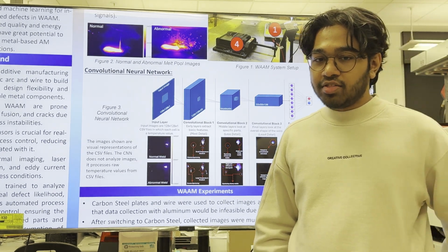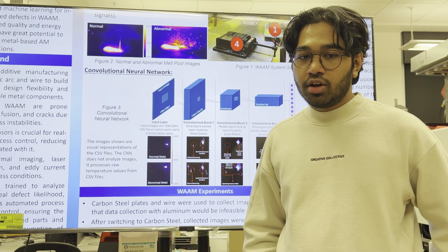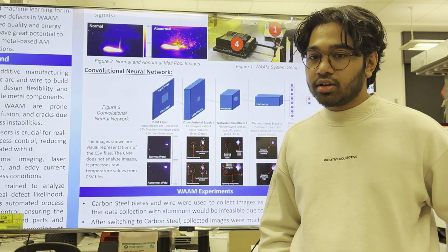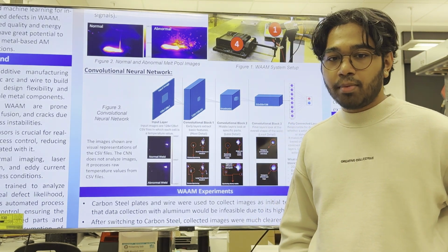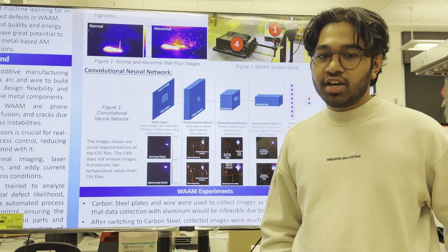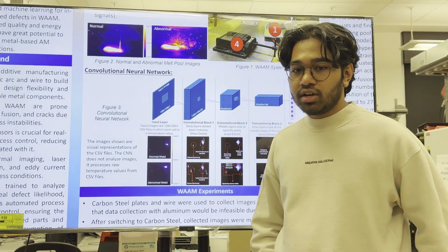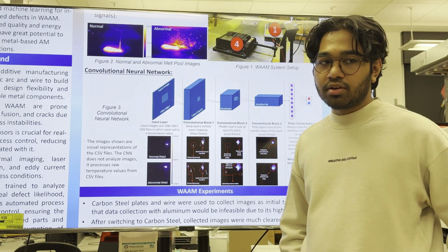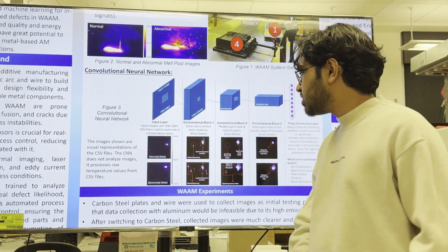And at this stage, the model starts focusing on specific regions of the image. It's not looking at every detail anymore. Rather, it's looking at parts of the weld. For example, it might try to analyze where spattering is most intense or where the edges of the weld are clean or blurry. Again, these features differ between the normal and abnormal weld. This layer helps the model understand these differences.